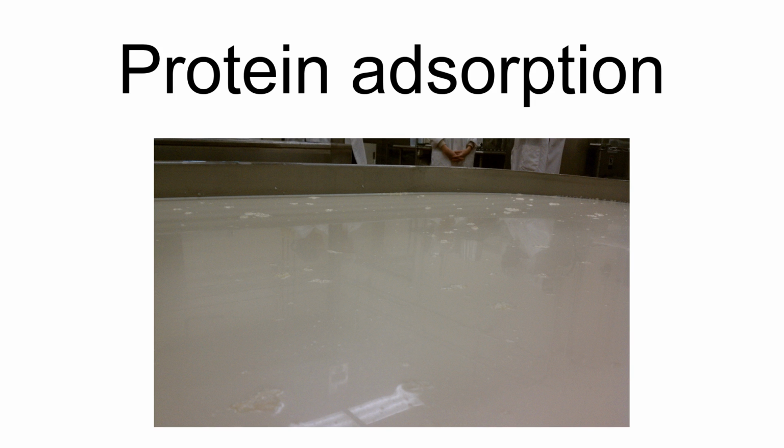polypropylene. Protein fouling is the gathering of protein aggregates on a surface. This is most common in heating processes that create a temperature gradient between the equipment and the bulk substance being heated. In protein fouled heating equipment, adsorbed proteins can create an insulating layer between the heater and the bulk material, reducing heating efficiency. This leads to inefficient sterilization and pasteurization.